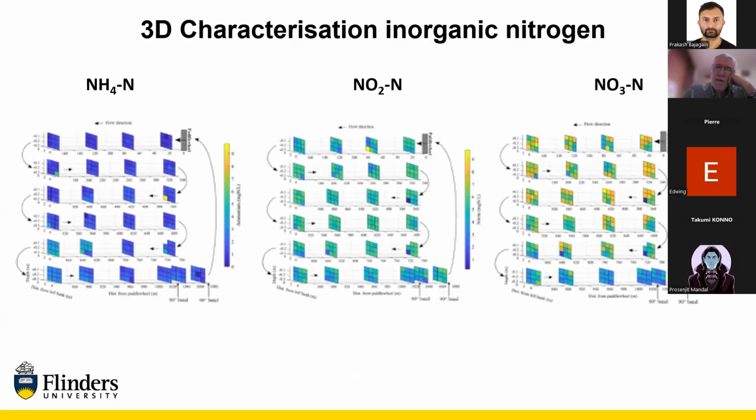So at the high pH that you'd expect during algal photosynthesis, the ammonia will actually leave the pond. So some of the ammonia will leave the pond and not be included in algal biomass or bacterial biomass. And that may well be what's happening here with the relatively low ammonia in the pond. It's very high coming in. Ammonia will be taken up by algae, and it will also be going out into the atmosphere due to the high pH in the pond system.